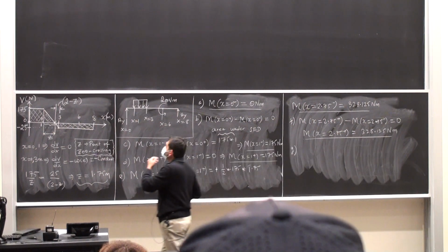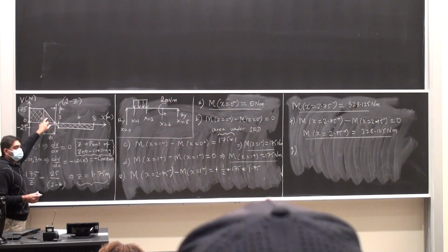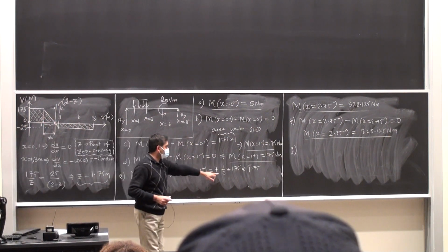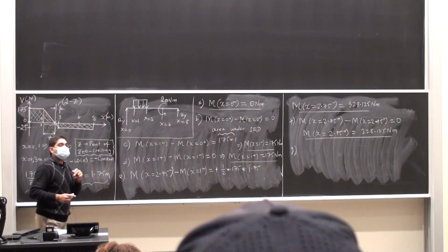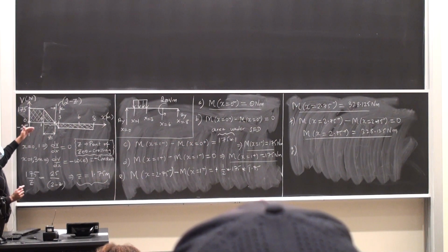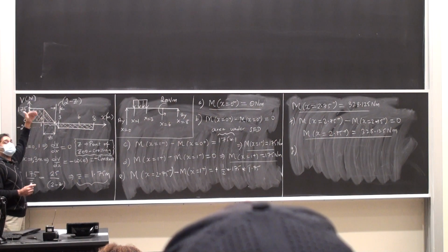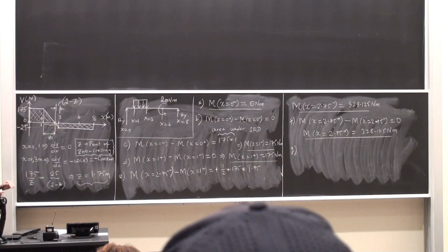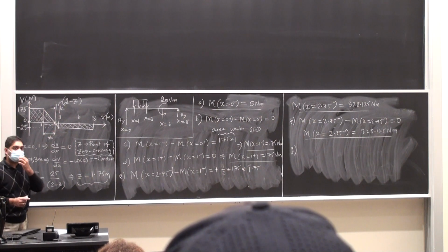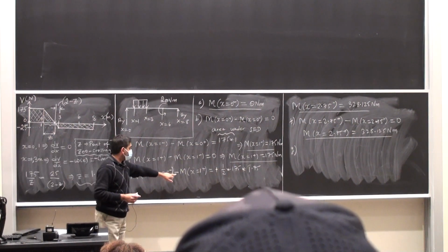Oh no, so this is a positive area. Right. So which is why I am saying it as plus half times 175 times 1. Oh, so we're adding them, we're not subtracting. You're not subtracting, right. So if the shear force diagram is on the upper side of the x-axis, that's a positive area. If the shear force diagram is on the bottom of the x-axis, negative. And that's regardless of the fact that you put a subtraction symbol there.